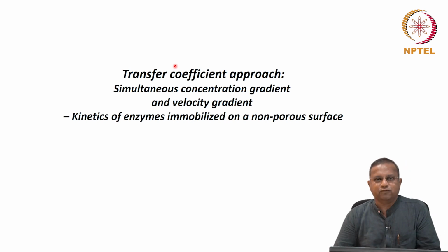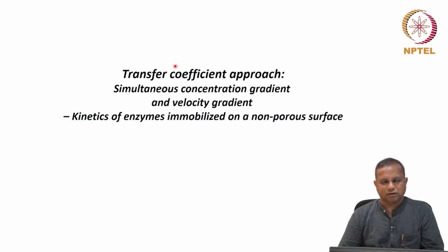However, it's very useful. It even gives us insight into the processes, and therefore, we are picking up that approach also. Today, we will continue with the transfer coefficient approach, simultaneous concentration gradient and velocity gradient. The particular example is that of kinetics of enzymes immobilized on a non-porous surface.